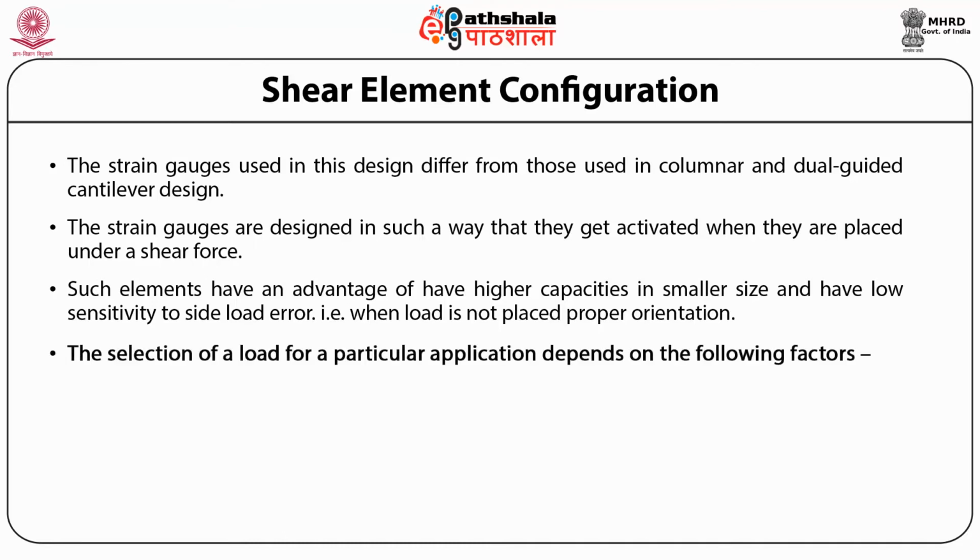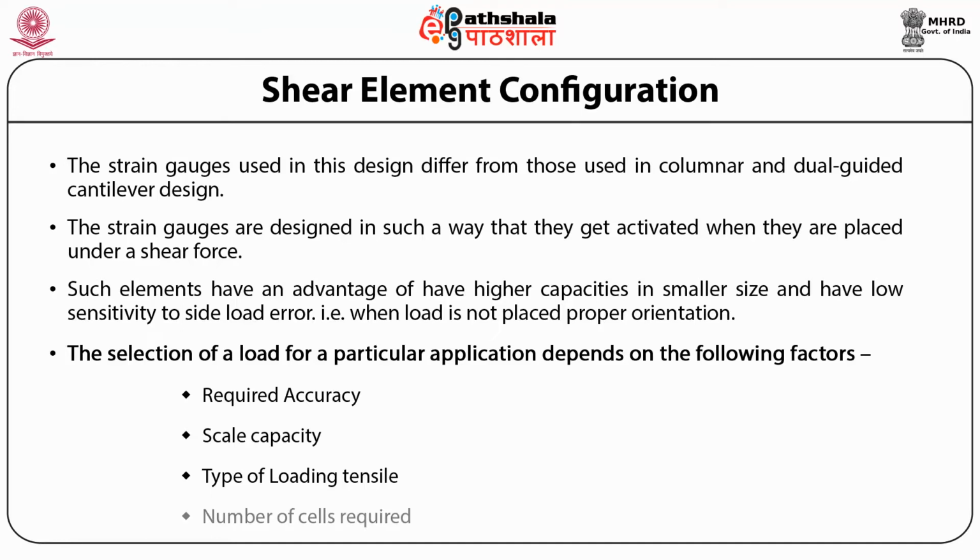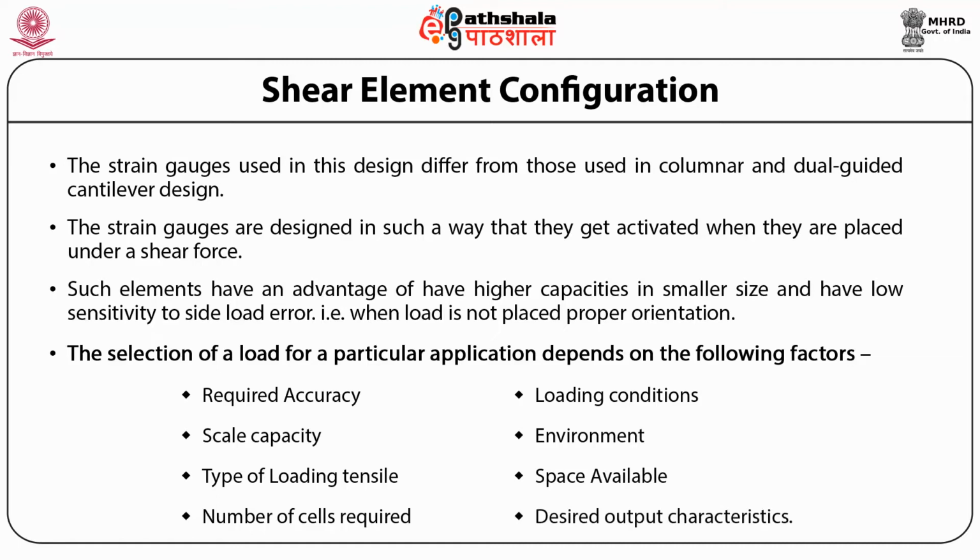The selection of a load cell for a particular application depends on the following factors. 1. Required accuracy. 2. Scaling capacity. 3. Type of loading, tensile. 4. Number of cells required. 5. Loading conditions. 6. Environment. 7. Space available. 8. Desired output characteristics.